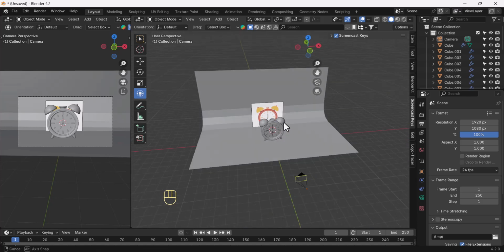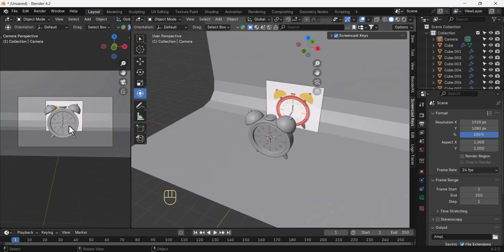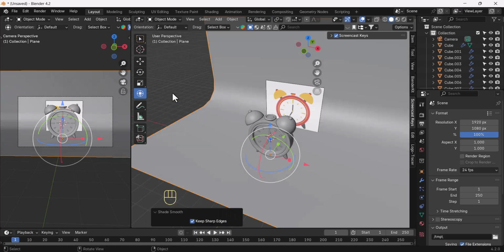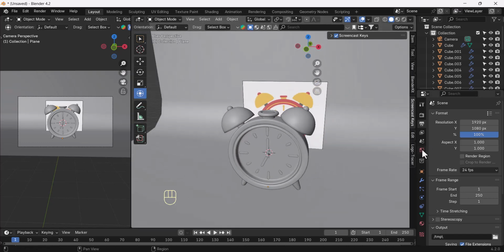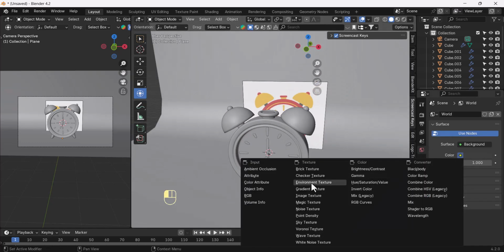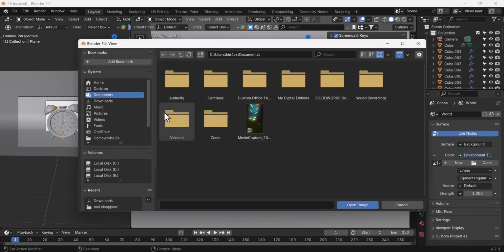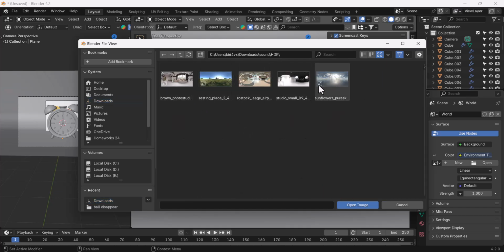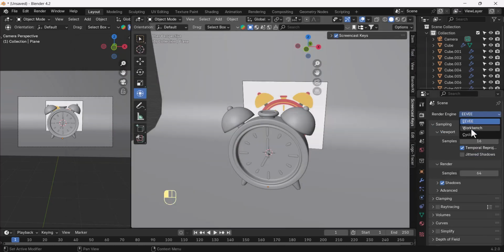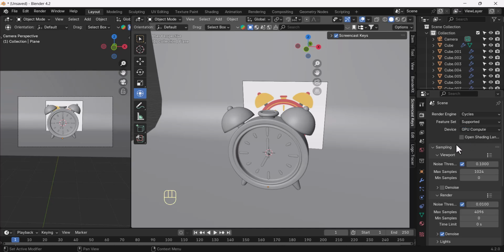Yeah. So simply, now we have to apply the colors, apply the materials, and here I'm going to use the HDRI for the environment. HDRI downloads. Which one are we going to use? We are going to use this one. Okay, and simply use Cycles and GPU and denoising. With this one, I'm going to use two, no issue, and just go to render view.